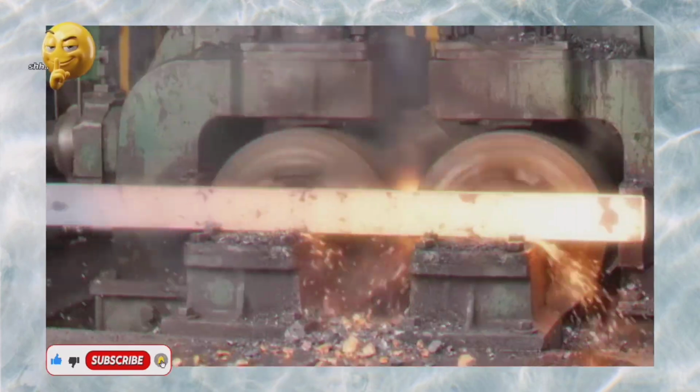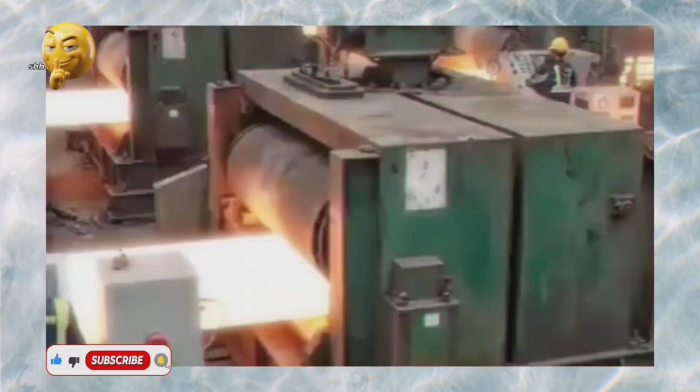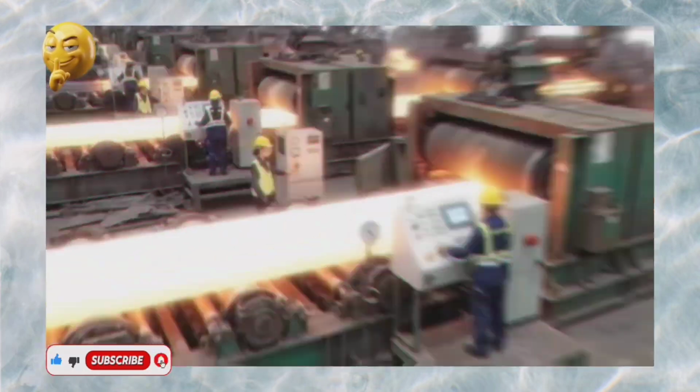These billets are cut to precise lengths, slowly cooled to prevent cracks, and inspected for internal and surface quality. They are the building blocks of wire rods. Chapter 8. Reheating the billets. Before shaping, billets must be reheated.